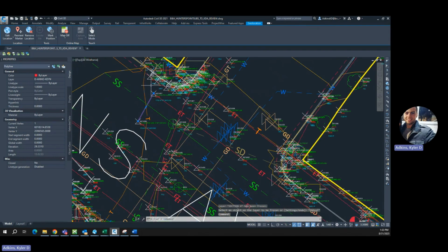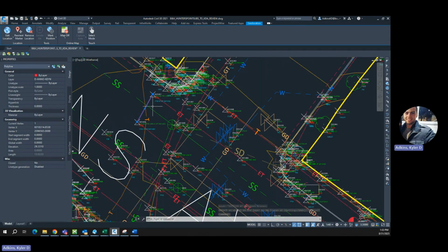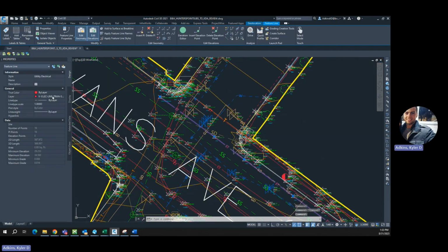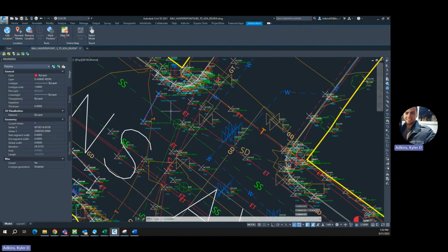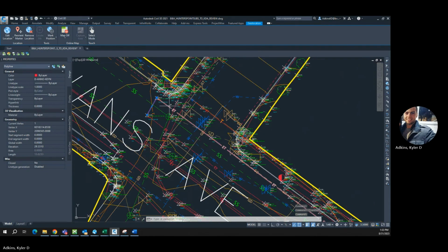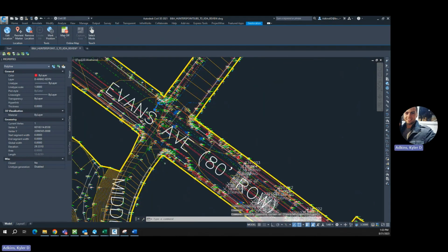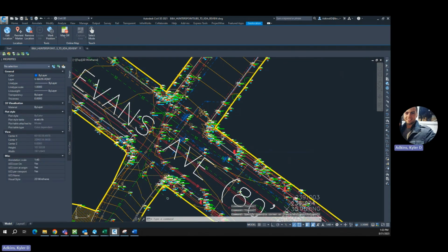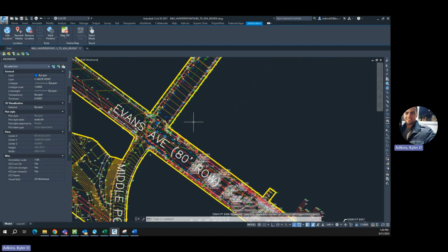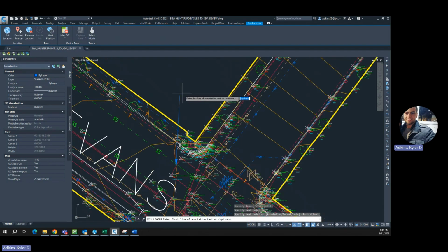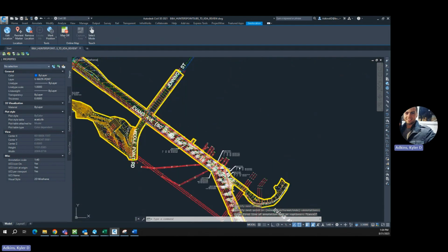So here's that layer that we just identified, and it looks like it should be part of this electrical line transmission. So yeah, that obviously was not assigned to the right layer. That's a good thing to flag. This laywalk command is very useful for survey checks. A good tip is to go down to the laywalk command and then flag those areas, create your own leader and flag a comment, and send it back to the surveyor to fix up.